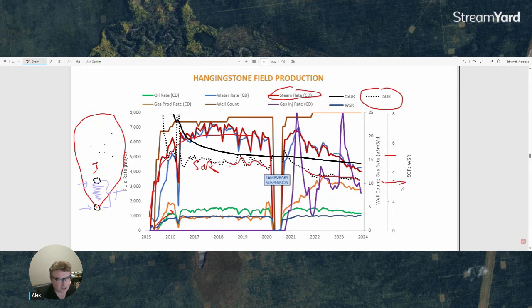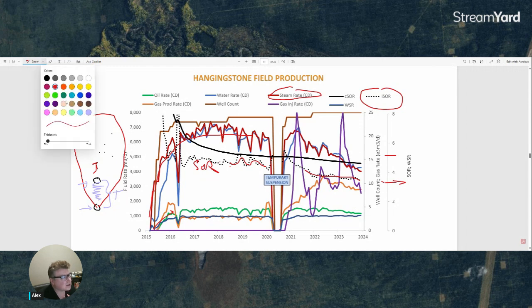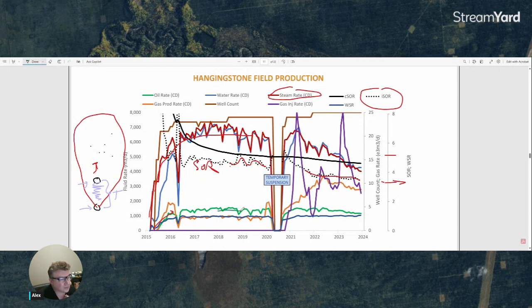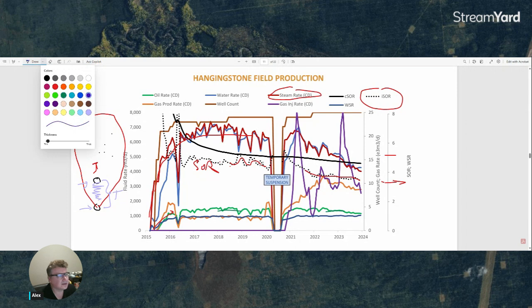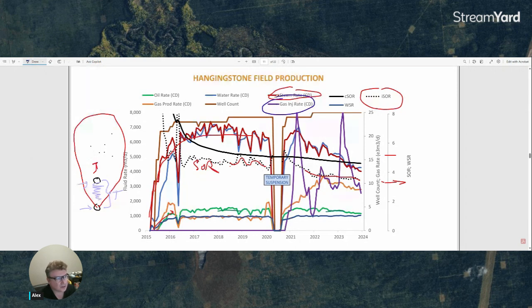So that speaks to the efficient performance of the asset, especially considering that the oil rate, which can be seen here, was not sacrificed significantly. But steam was declining. But why? Because in purple, we can see the signs of NCG co-injection, which is gas injection. So in late 2021, you can see a big uplift in NCG right here, in the purple line, and basically steam reduction.